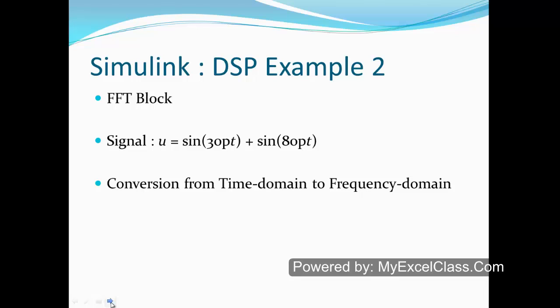Okay, now we are gonna do another example, but this time it will be using Matlab Simulink. In this example we will be plotting the FFT of a sine wave, and what we'll do is convert from time domain to frequency domain and plot it. In the model, the sine wave will be generated into frame based sinusoids. One is 15 Hz and one is 40 Hz, and the sinusoids are summed point to point to generate combined sinusoids.